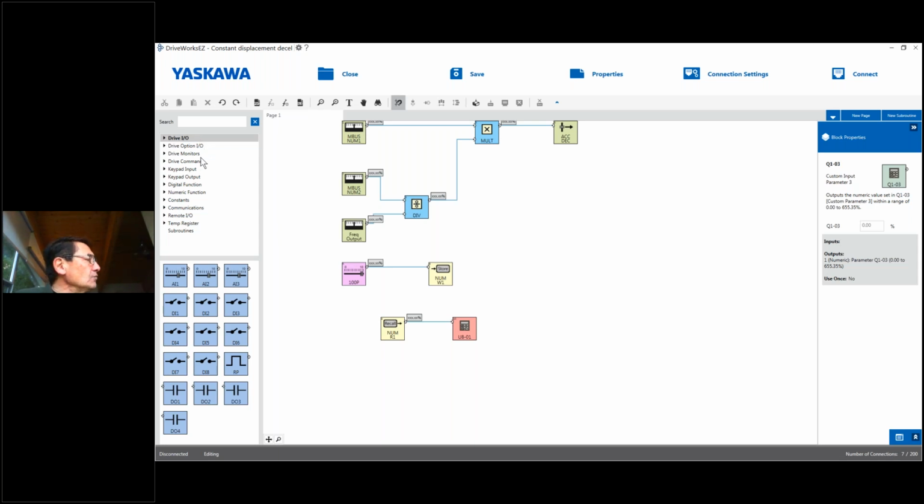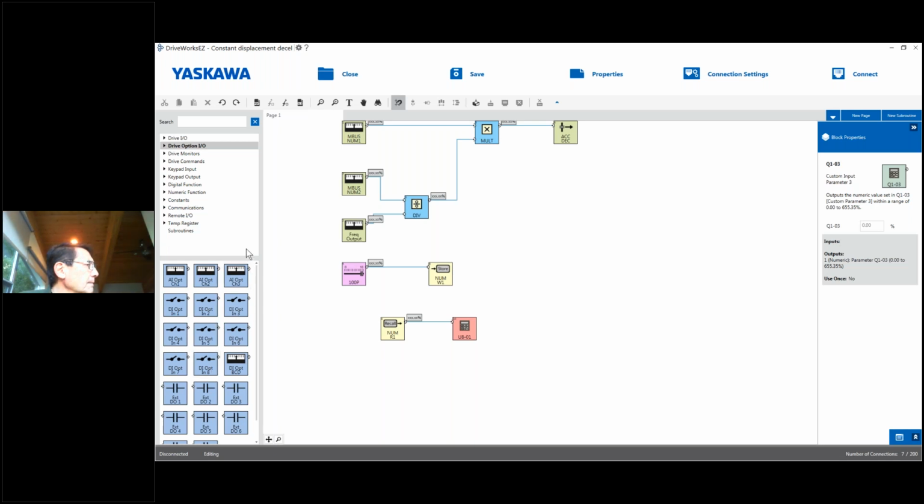But I'm on a GA800, so it's going to show me the 3 analog inputs and the 8 analog outputs up to 16, actually up to 18 with a DI option card. That's odd. Why is that? I'm sorry. Digital input 1 through 8. It confused me for a second. Here are the optional. You can add another 8, so you can get a total of 16. Back to the standard I/O.